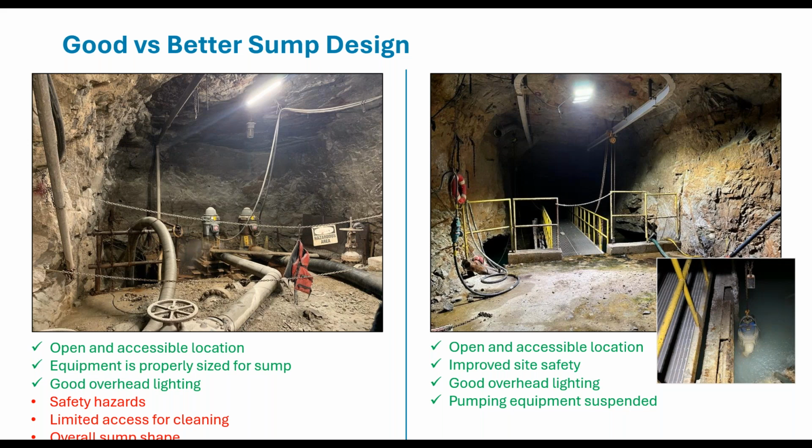But there are still some safety concerns here. We do see the hazardous area sign on the chain going across the screen and a life vest hanging there, but there are still several trip hazards with the way that the discharge piping is laid out. You can see some partially buried pipes that would be hard to identify, especially when you're holding tools or looking at the pumping equipment that you're looking to service. There are power cables hanging right above those pumps that really could be managed in better ways. So there is opportunity for some improvements in how this is laid out.